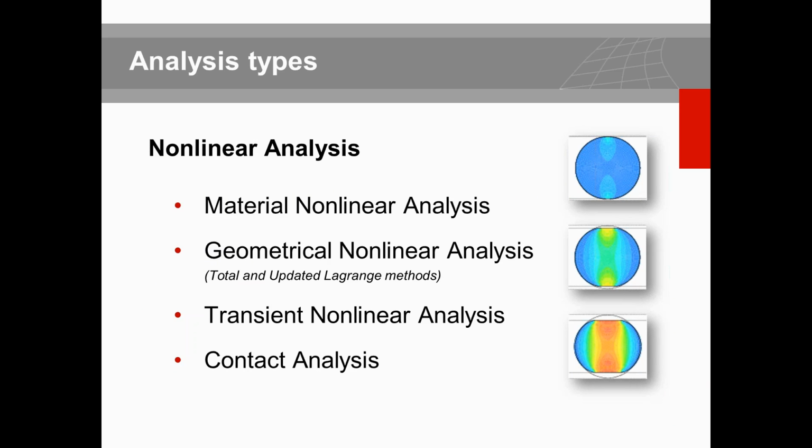For nonlinear analysis, we have different definitions. This nonlinearity can be defined at the material level or at the geometrical level, or this nonlinearity can be defined with time. So you may also consider the nonlinear approach on implementation for contact analysis. By variation of the load, the algorithm that finds a new contact surface is nonlinear, therefore you can perform contact analysis, which is nonlinear analysis.